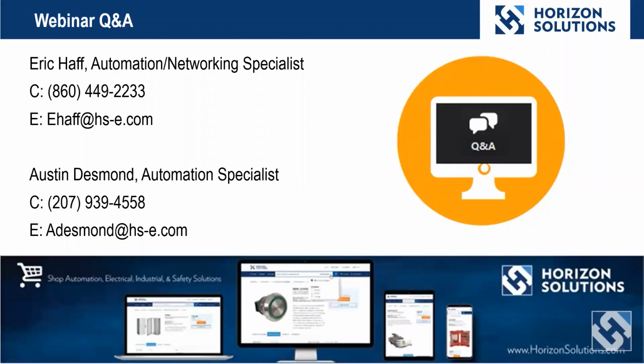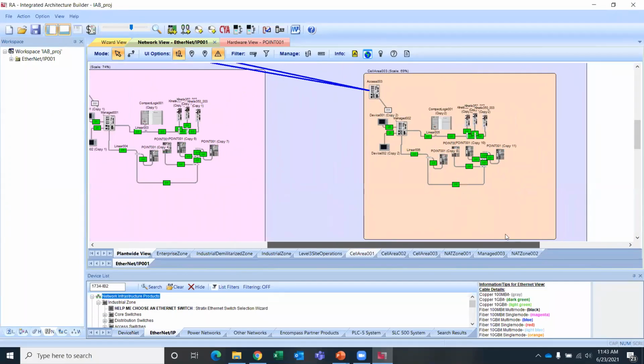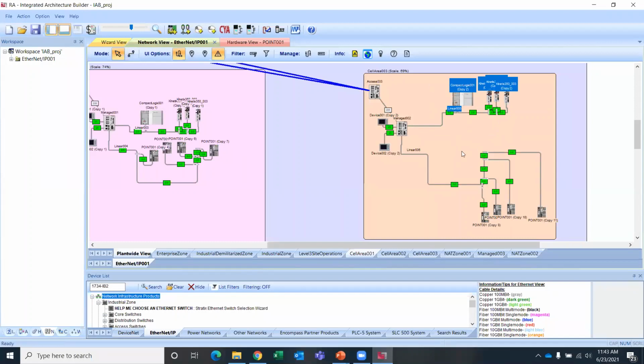Excellent, thank you. And it looks like we have one final question. Do we have the ability, once a network is created, to convert from linear to a ring topology? Absolutely. One second. That's a great point. That's another great reason to utilize this, because you can go into the connector tool here, start with a blank canvas, put a bunch of devices in here, and just use the connector tool to connect everything up and do home runs and things of that nature back to your switch.